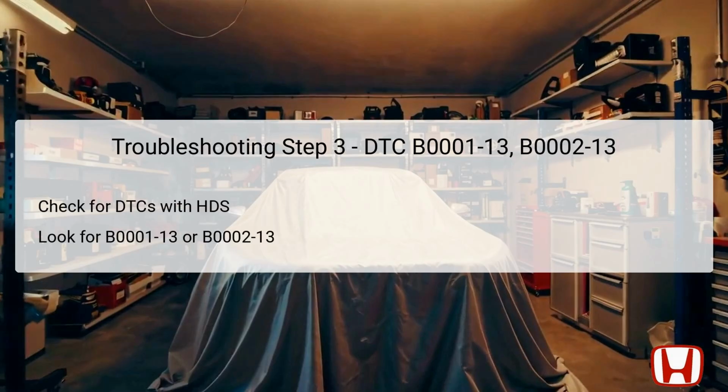In the third troubleshooting step, you will again utilize the Honda Diagnostic System, HDS, to check for any Diagnostic Trouble Codes, DTCs, that may still remain after clearing the previous codes. This involves a crucial step of verifying whether DTC B0001-13 or B0002-13 appears once again. If either of these codes is indicated, it confirms the persistence of the problem that requires further investigation.